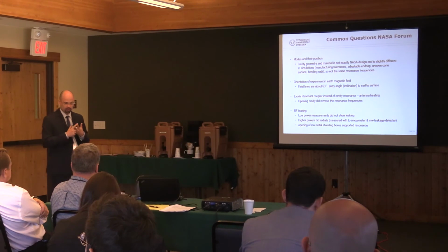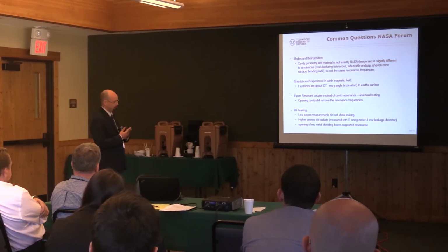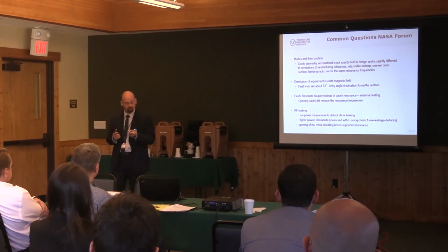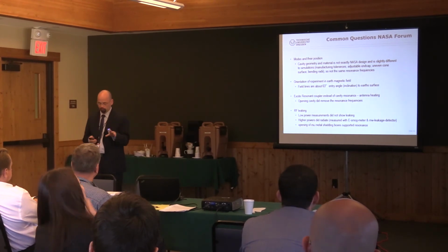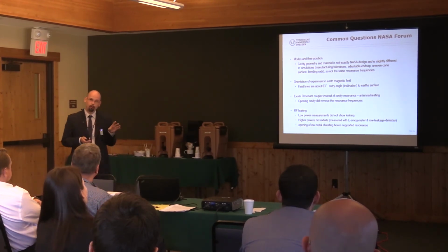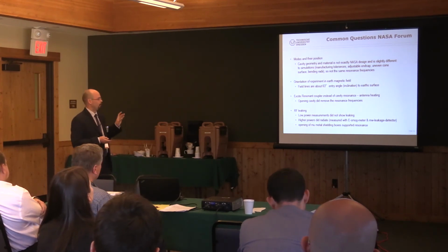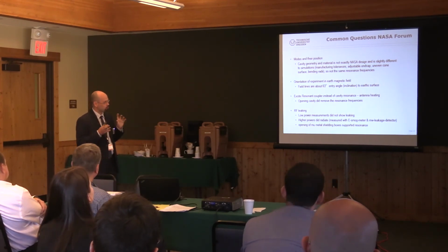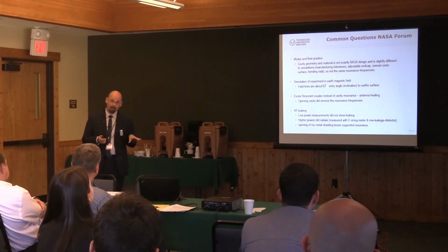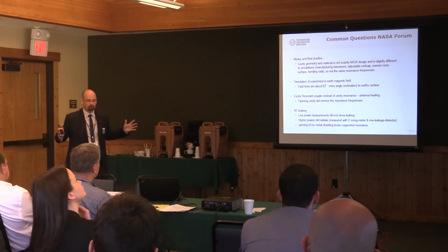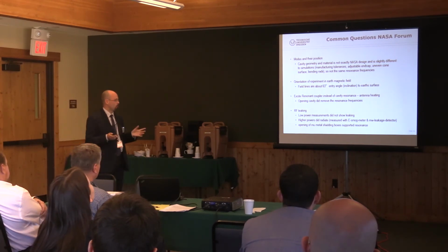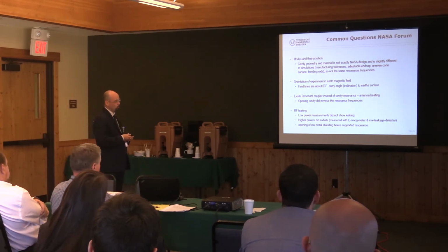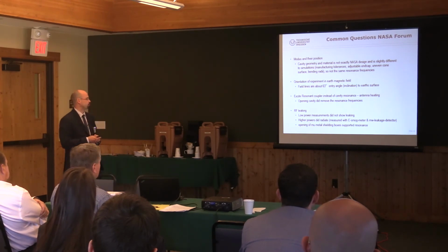To detect this we used two kinds of power meter, electro smog meters, let's say. A very fine-tuned one with up to 2000 microwatts per square meter, and a very strong one with about 2 milliwatts per square centimeter. So we've got a huge range of RF power scanners to look at our cavity, and as I already said, we saw quite weak radiation from our cavity.